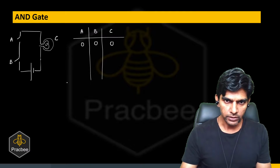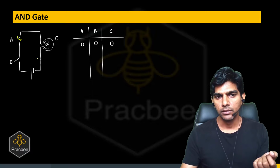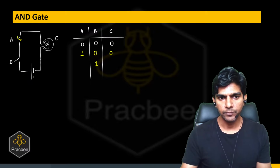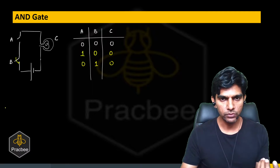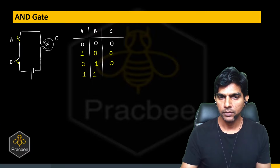Now, if I close the switch A, the circuit will still remain open. So if A is 1 and B is 0, again we get a 0 output, so the bulb will not glow. Suppose we close B and keep A open, in that case again the circuit is open, the bulb will not glow, we'll get a low output. Suppose both the switches are closed, so we have high inputs. In that case, there will be a current through the bulb and it will glow. So we'll have a high output.